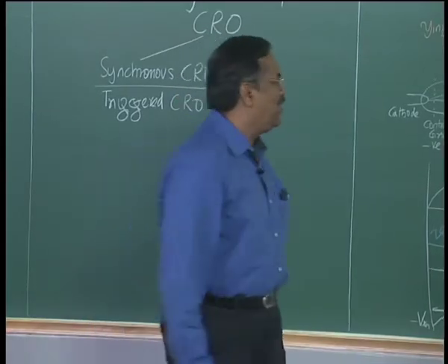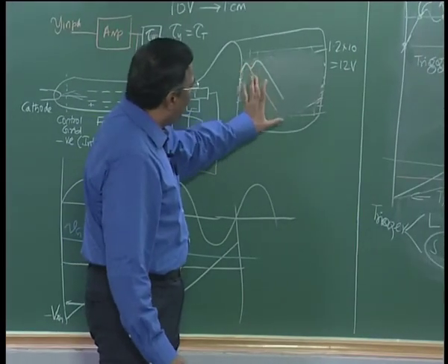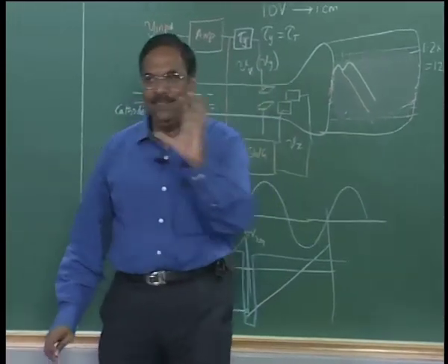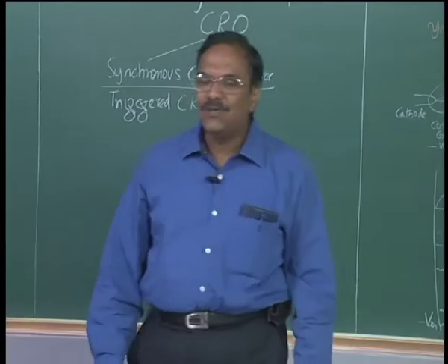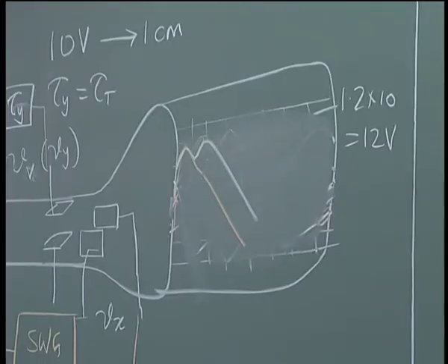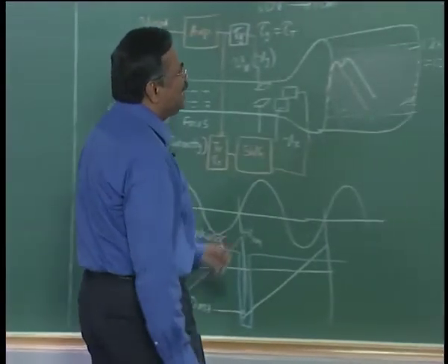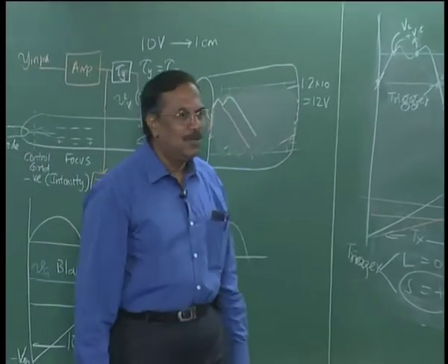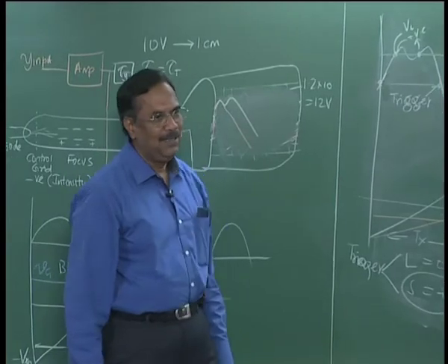So, then what we will see is, for one sweep this waveform may be shown, the other sweep this waveform will be shown, and you will see the waveform moving like this, right, which means the level and slope for the trigger that you have chosen is not uniquely defining a starting point on your waveform. So, one way is to reduce this level, right. Okay.